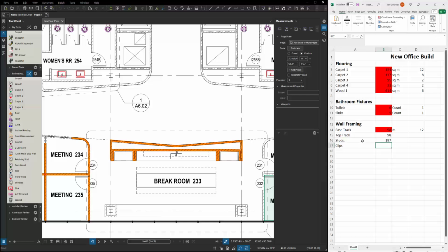And there you can see it's counting according to the spacing I put in the formula how many studs we need. And then for clips, if you have one top and bottom of each of those studs, then this one's just going to be equals, and I'm not an Excel expert, I don't know if you need the parentheses in here, but we're going to do that, and we're going ×2 on this one to give us the number of clips. So you can start to build out assemblies.